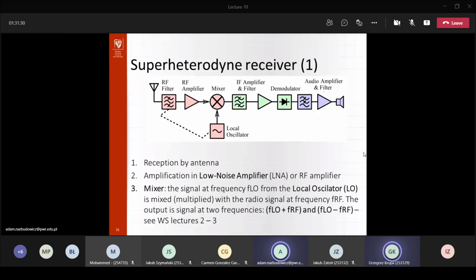Yeah, I know what you mean, but I've heard that the very old receivers for AM and shortwave had the problem, even before the war, that a very low IF introduced a whistling noise at short waves. If the intermediate frequency was around 200 kilohertz, it was better for long wave to reject the mirror images. But for the higher frequencies, the mirrors were so close that you could sometimes listen to them.